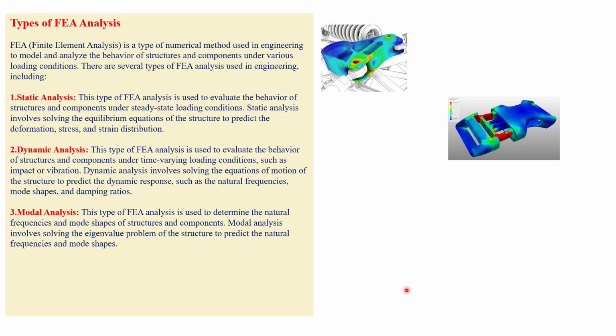Let's say we have the whole automotive model, a car, the vehicle. There are so many connections, right? And the contacts you're going to use: nuts and bolts, washers, adhesives, everything, RBE2s, RBE3s and all. So thousands of components will be connected. If you do the modal analysis with respect to mode shape, and a component is flying, then you will get to know whether the entire assembly is modeled properly or not. So this is the main reason we use the modal analysis to deal with the complete trims.